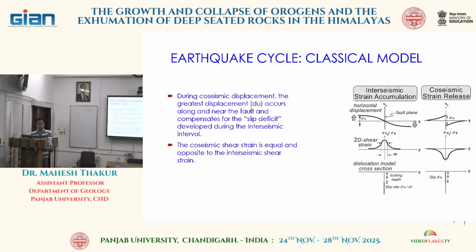Different types of faults. In this case, again, displacement compensation along multiple faults. We have these multiple faults interacting, and we can have the combined throw. Again, these two faults are merging, and then we can have the damage zone in between those two faults.